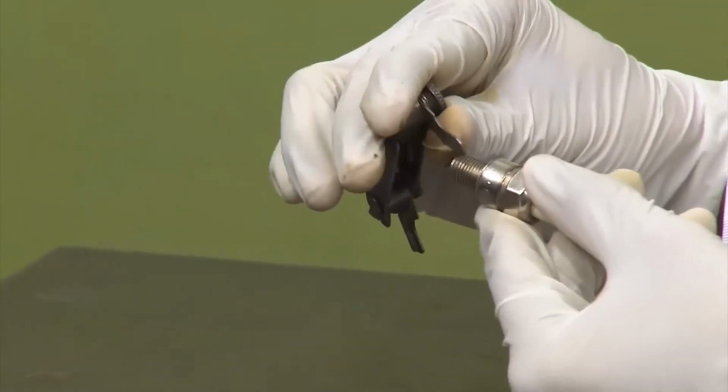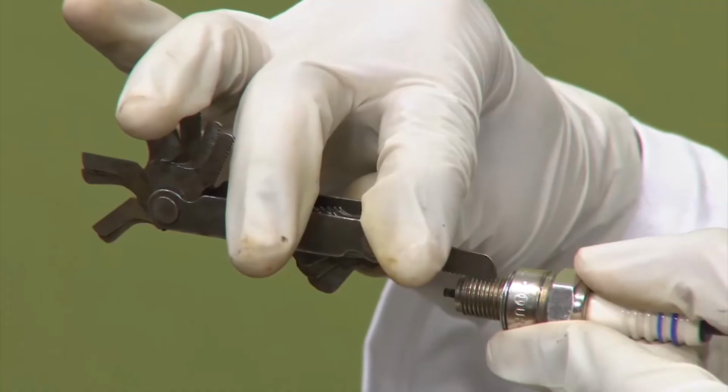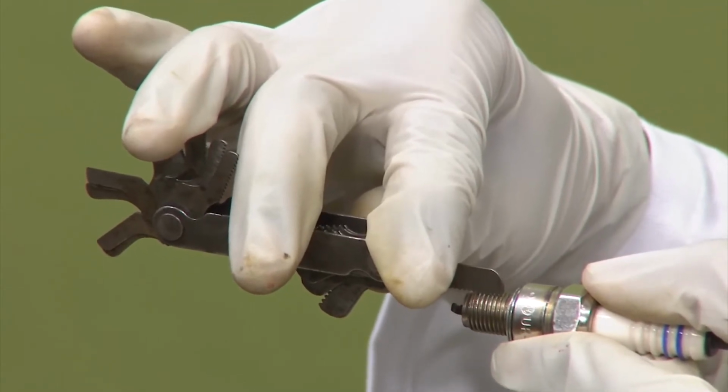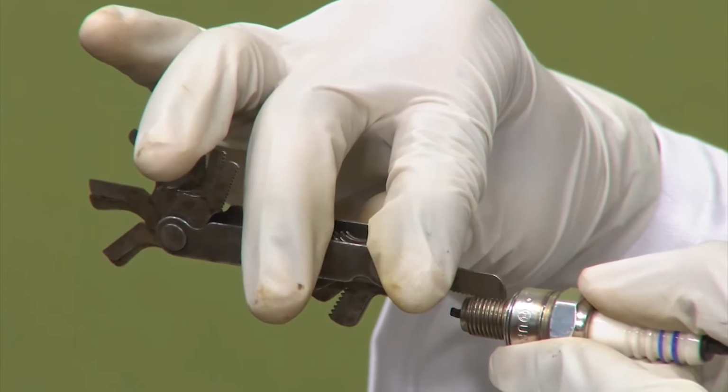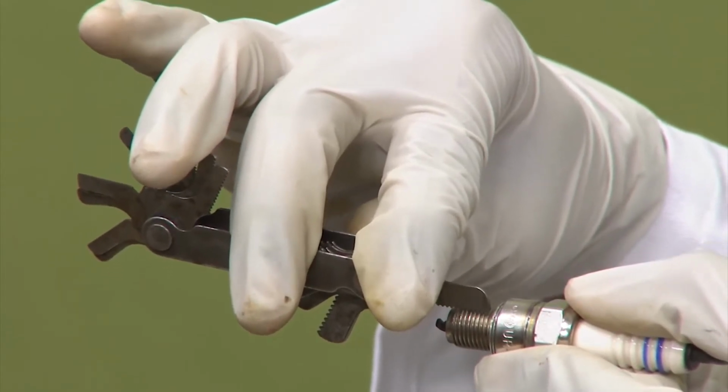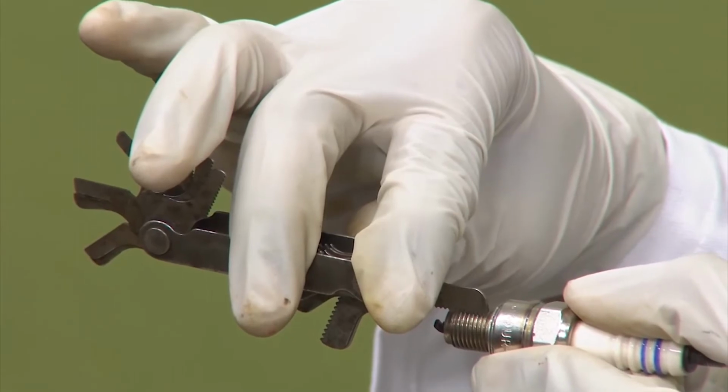This size is 1.1 mm pitch. So, you can see that 1.1 mm is a little larger. The pitch on the leaf of my thread gauge is a little larger. So, let us try 1 mm.